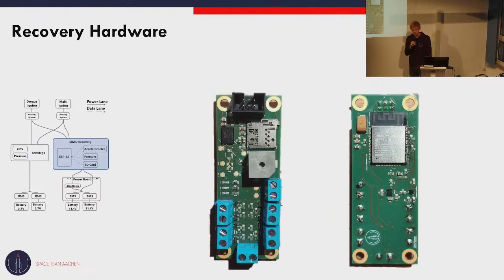First of all, we're going to take a deep dive at the self-developed board. Our self-developed recovery board has currently a first working prototype. It's actually quite compact and can do a lot of things. We have a total of 4 high-power outputs, which can trigger parachute events. We have 2 sensors, a barometric pressure sensor and an accelerometer, which both serve to finding out whether we have reached apogee or whether we are at around 400 meters to deploy the main parachute.